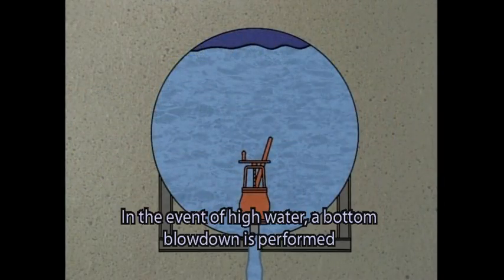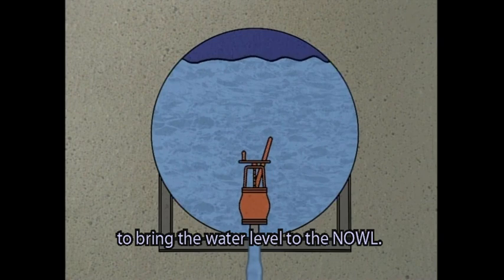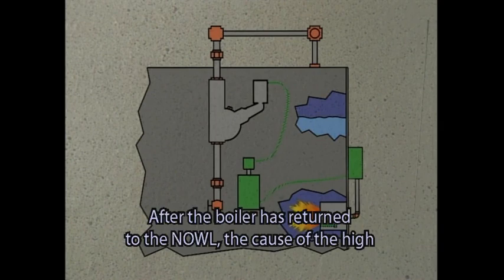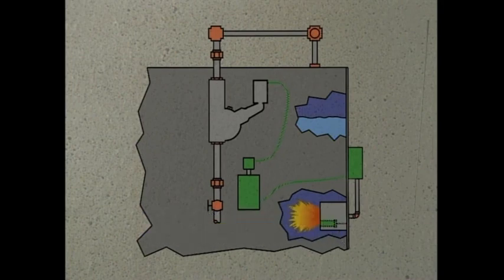In the event of high water, a bottom blowdown is performed to bring the water level to the NOWL. The burner firing rate should be reduced. After the boiler has returned to the NOWL, the cause of the high water condition should be determined and remedied.